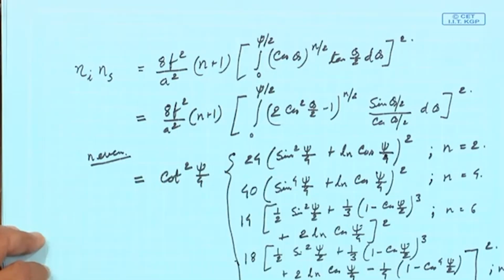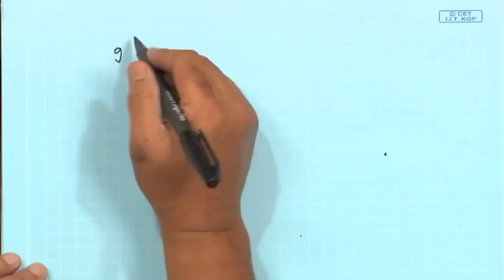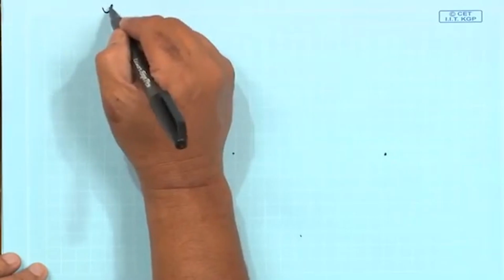Now, while deriving all this, we have assumed uniform field illumination in the aperture, but obviously with a cos to the power n theta type of excitation, there will be taper. So, what will be the taper, that also we can calculate, that what will be the amplitude taper in the field. So, let us say that we have chosen from this figure some optimum psi value.